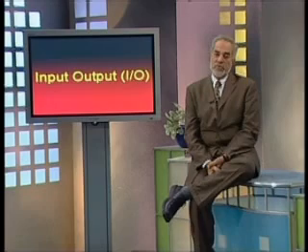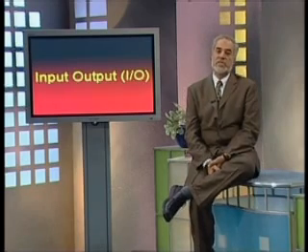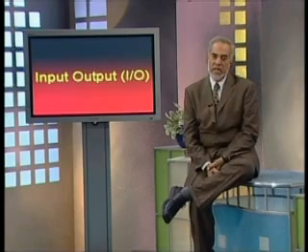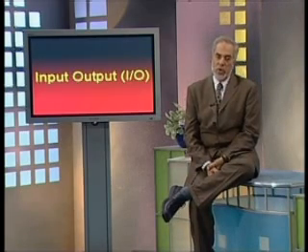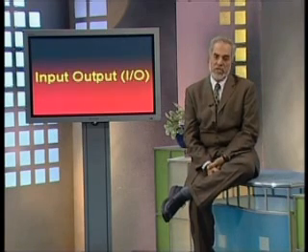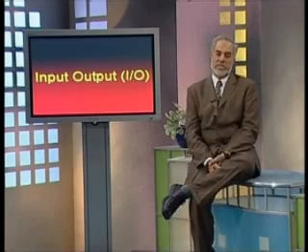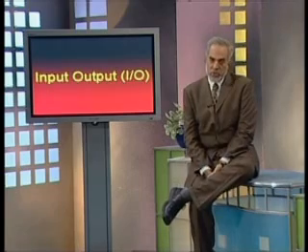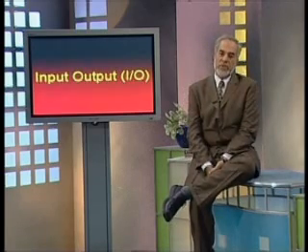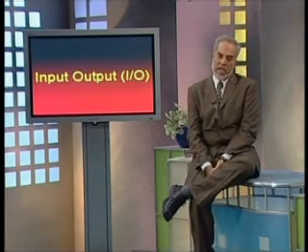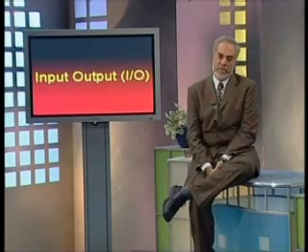Now, in the case of interrupt-driven I/O, though the efficiency improves, it is better than the programmed I/O. Nevertheless, there is a problem. The problem is that all the data goes through the bus of the CPU, and therefore the CPU cannot take any other activity during that particular time. So, therefore, in order to reduce the burden on the CPU from the I/O device, we could have a third option, and that is DMA, or direct memory access.